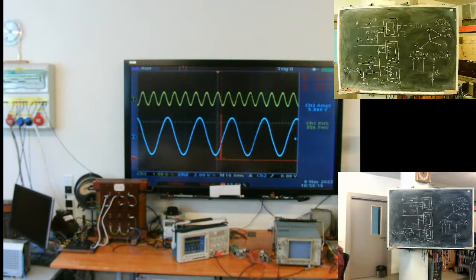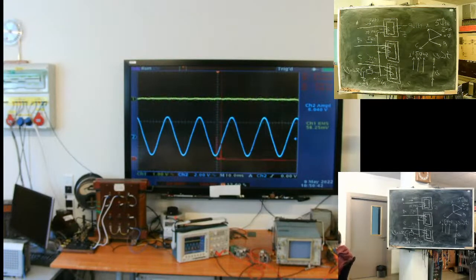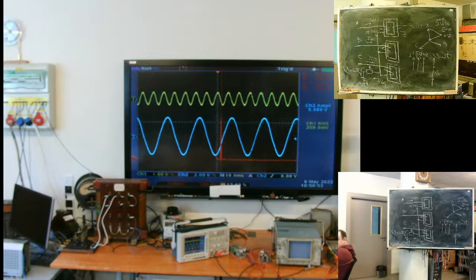What will happen if I disconnect the neutral wire? Now we see third harmonic flowing through the neutral. If I disconnect it, can third harmonic flow? No. And we will see the same situation that I modeled with my coil. Look. You can see distortions in the secondary voltage. Right?